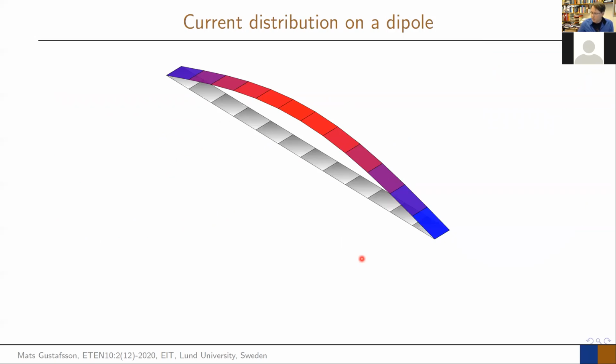So then we're going to determine now our dipole. Again, go back to our dipole. This is the long piece. I drew before that the current density looked like a cosine function around here. We just assume it is like this. We can validate it against solutions of Maxwell's equations, but here we say, okay, it looks like this. And now I'm going to ask, how does this current radiate?